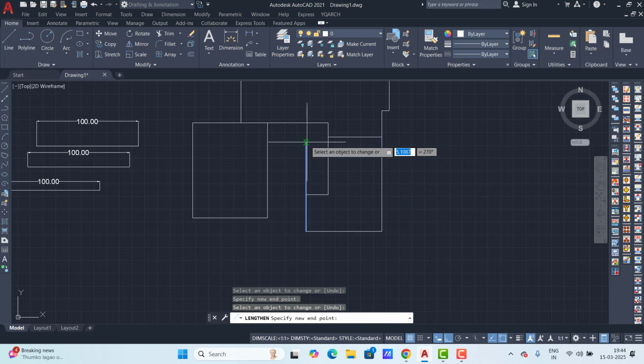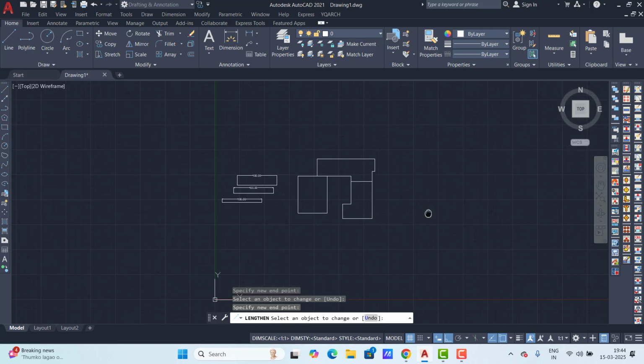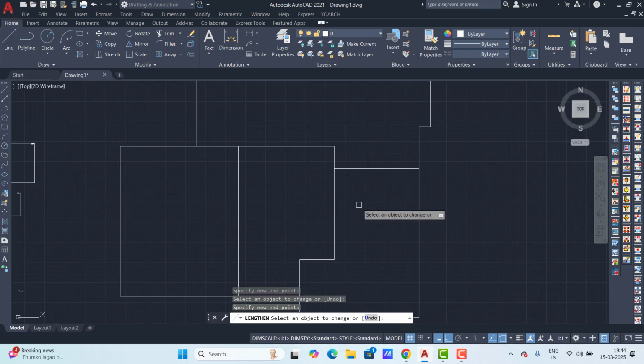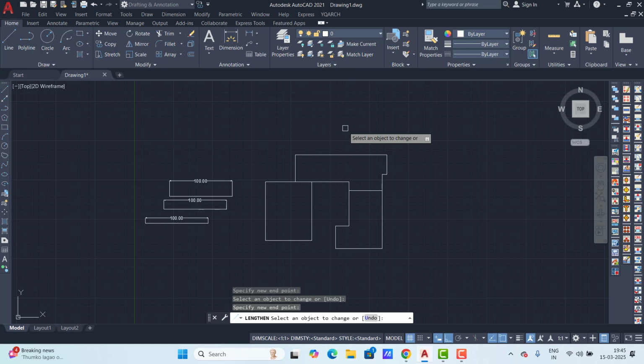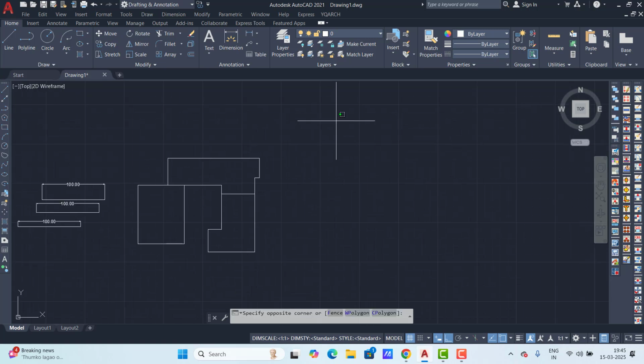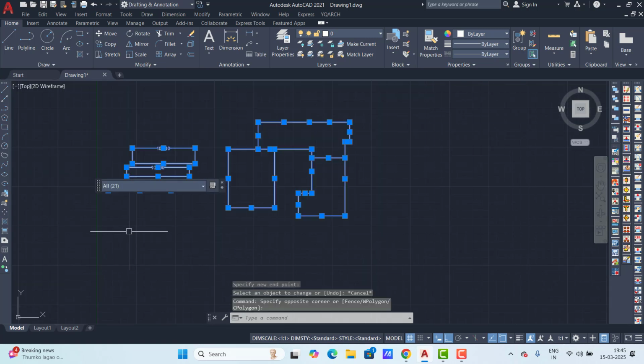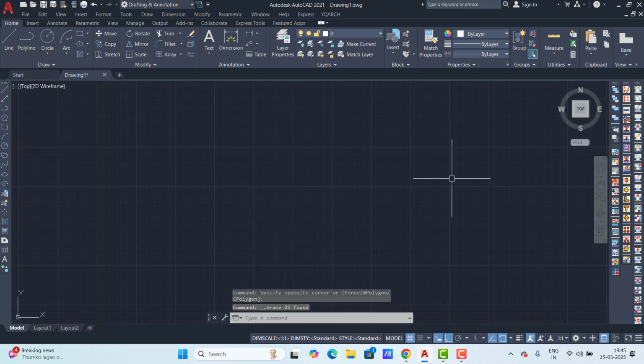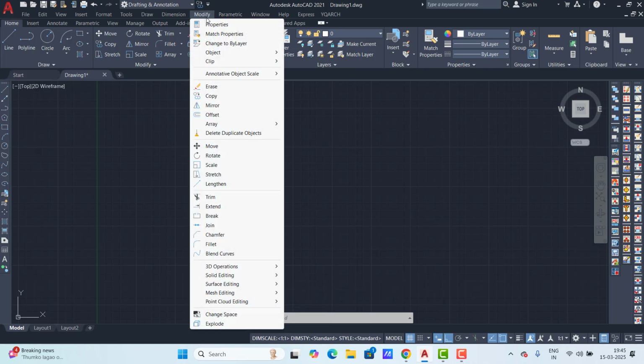After clicking, we can see multiple styles and patterns here. Whichever pattern you want, you can select it. When you select a pattern, the scale factor is too low, so we manage the scale factor here. If you change the scale factor, the pattern quantity increases or decreases. Now see, the brick is coming horizontally. The pattern design is this way. I want to change the angle direction, so you change the angle here.